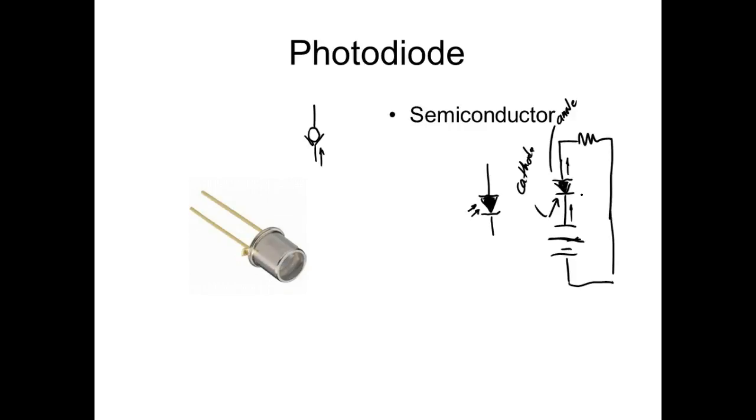Now, it's solid state, so it's going to drop a little voltage. These guys here drop about 7/10 of a volt. Some books teach 0.6, some teach 0.7. And so if this was 24 volts, then we would measure 23.3 volts right there, which basically is everything, right? Understand? So you have a little drop. All solid state devices, these guys can act like a switch, but they will always drop a voltage, always. So they are not switches, they're solid state.